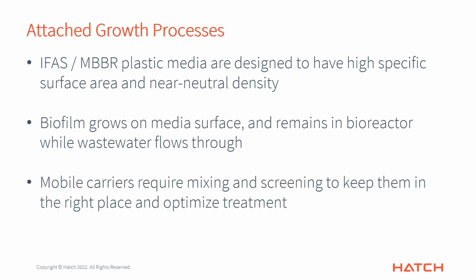These systems require a certain amount of careful mixing to be able to make sure that, first of all, you get the media itself spread all the way around through the tank and optimize that process so that you can get exposed, first of all, to all of the wastewater coming in. You want to make sure that you've mixed all of that biomass that's on all those surfaces so that it gets interacting with the bulk liquid that contains all the ammonia that you're trying to get rid of, for example.